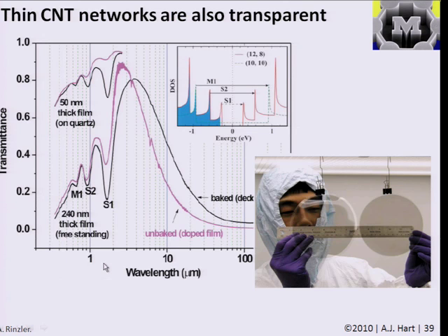And another interesting and useful attribute of these thin films is that they can be transparent. And this shows an example from work from several years ago, the first paper that was published on nanotubes as transparent conductors. And if you have a very thin film of nanotubes that is electrically conducting, it, of course, doesn't have a very high volume fraction, so you can, in fact, still pass light through the film and pass electricity through it. So there's significant work on development of processes for making high conductivity, uniform thin nanotube films also as transparent conductors for applications as touch screens, for phones and things like that.